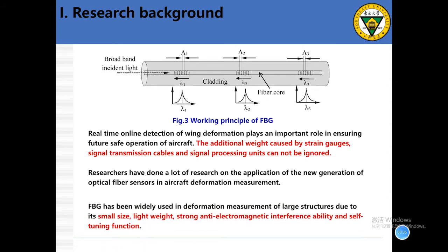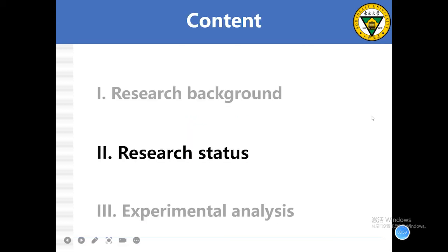FBG has been widely used in deformation measurement of large structures due to its small size, light weight, strong anti-electromagnetic interference ability, and self-sensing function.